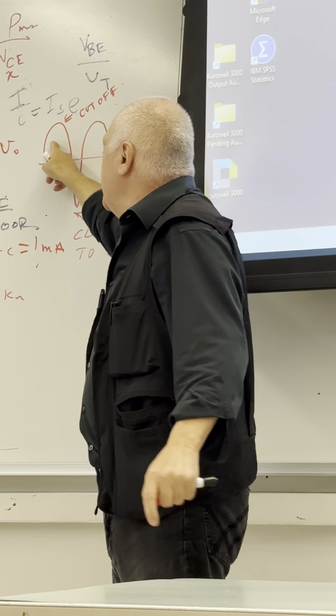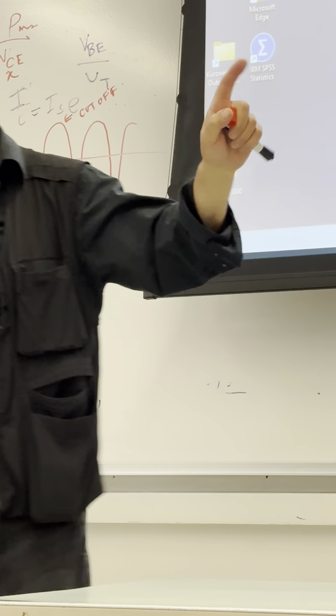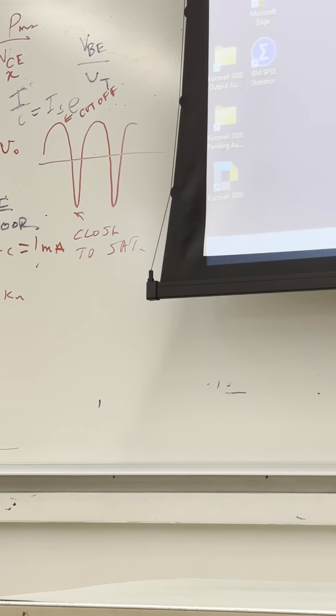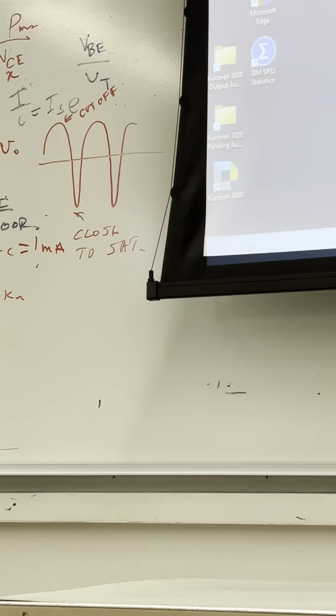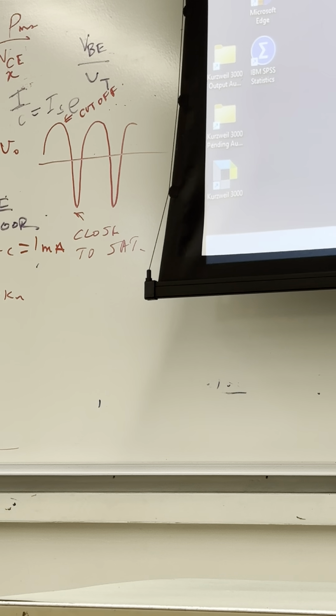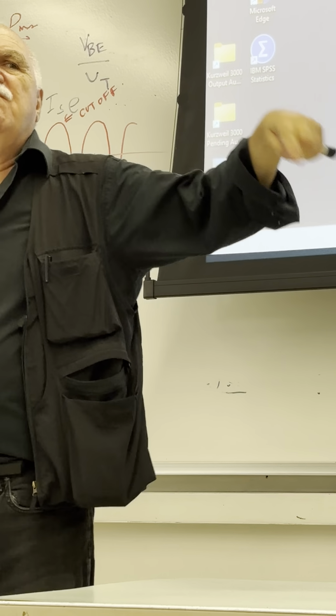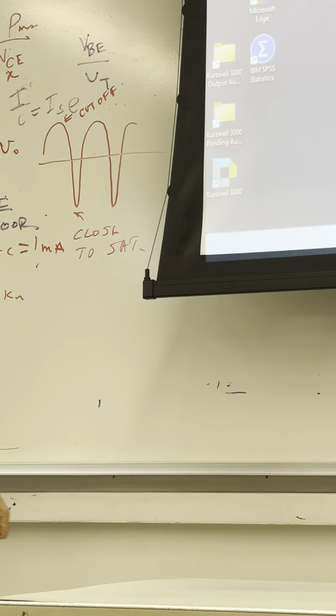Although the N and the P calculate the possible swing, giving you a size, it's not a useful limit. Maybe you use half of it. It's good enough, you see? So if your N and the P calculation tells you, oh, you can get 7 volt peak to peak out of the output, you can get 7 volt peak to peak, but the quality of the signal will be lost. You'll get too much distortion there. You use maybe 50% of that maximum. It's a practical one, 50%. So if it's 7 volt, don't drive it to more than 3.5 volt peak to peak at the output. Keep it to that limit.